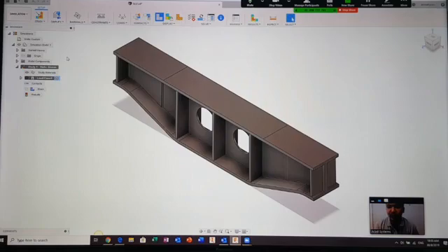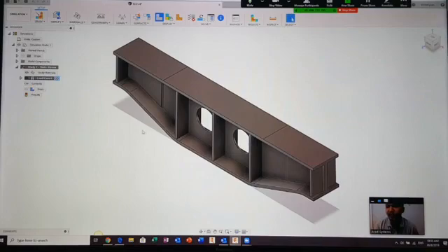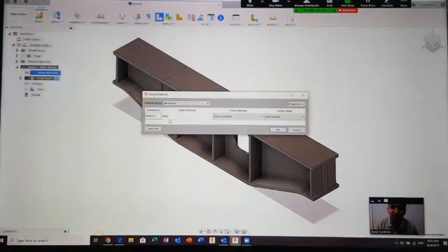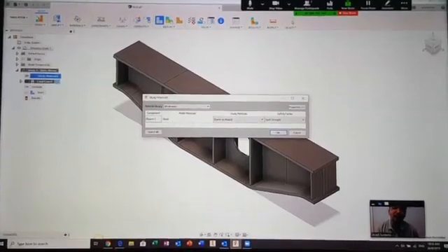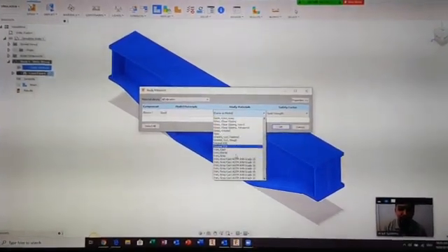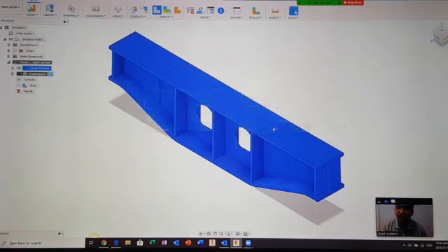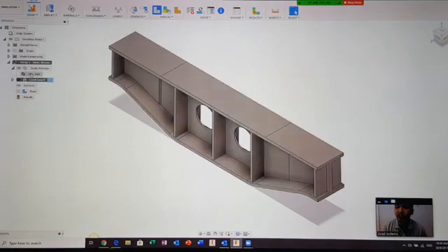static stress environment. Okay, so what we need to do is we need to have the material here and the constraint here and also the load here to put it inside our study. So the first is I'm going to use the study material. Let's say I'm going to edit the material. Now I'm using steel. Let's say I'm not going to use steel. I'm trying to use maybe cast iron, for example. Then I just hit OK here. Now my study material will be cast iron.